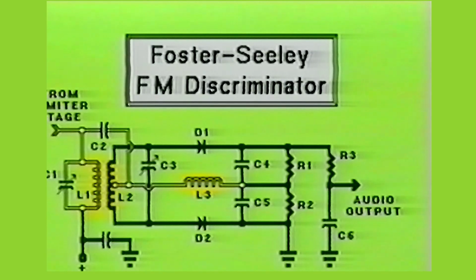The signal being applied at inductor L1 is electromagnetically coupled to inductor L2. The voltage induced in L2 causes a current to flow through the coil, which is in phase with the induced voltage. However, the current flowing through the coil also develops a voltage across the coil, which will lead the current by 90 degrees. This places the voltage across inductor L2 90 degrees out of phase with the reference signal.